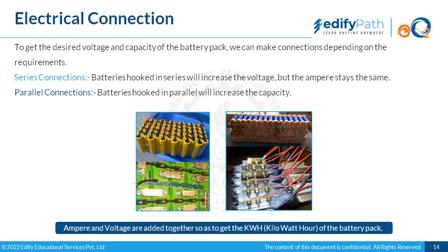When we have assembled the battery pack, each and every module would be connected to the BMS through a control cable. The BMS has input ports through which every module would be connected. As we said, every BMS is rated for a certain current and for a certain number of series ports. So that many modules we can connect in series with the help of this BMS.